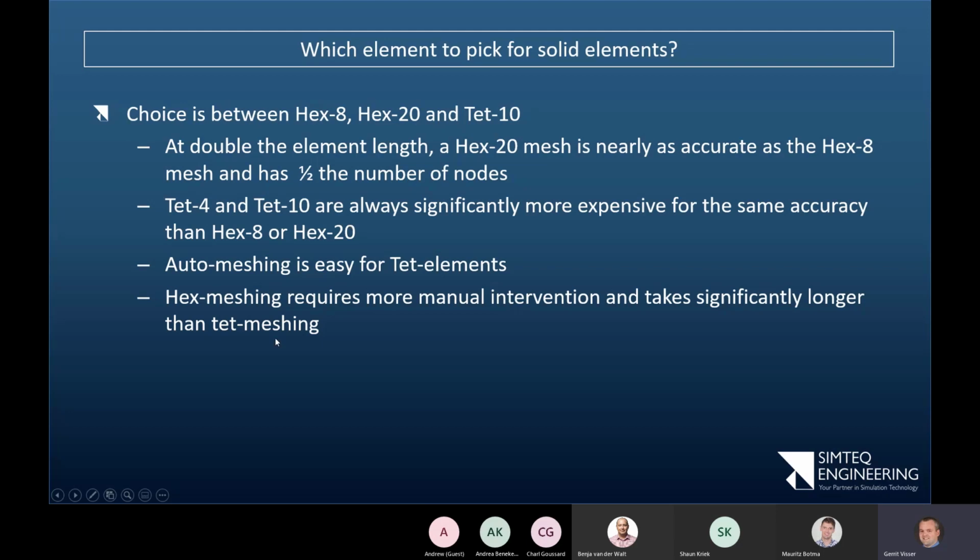Okay, so for any hex meshing, or most hex meshing, we need some form of manual intervention to help break it up into more manageable sections that are extrudable to generate the hex meshes. Yes, I know there's a couple of supposedly newer methods that use a core of perfect hexes and then transition on the outside to either pyramid elements or TET elements.